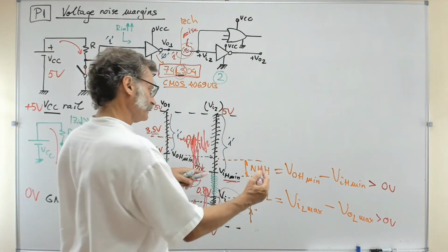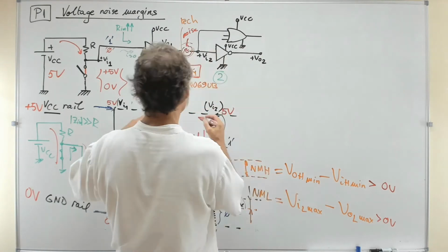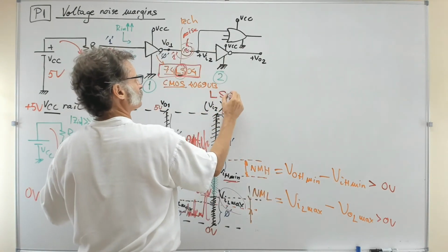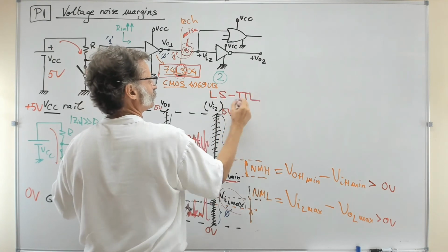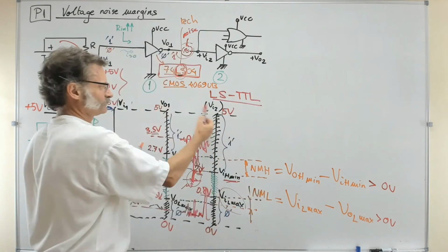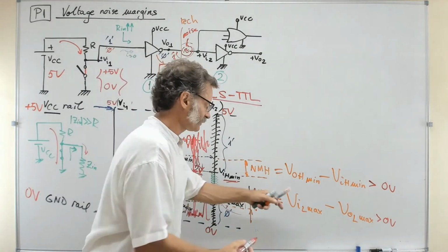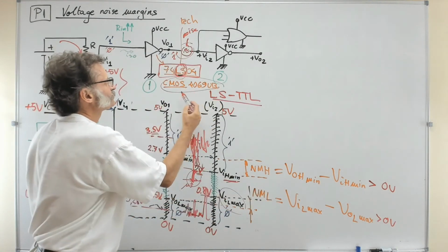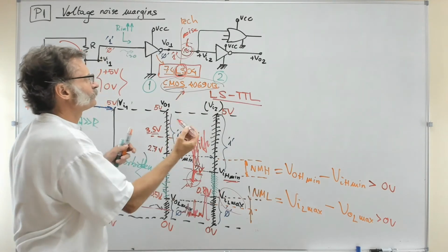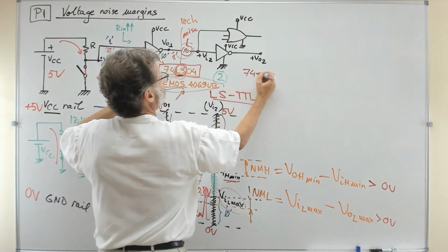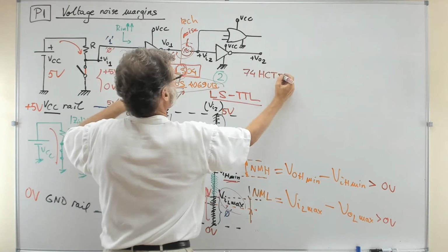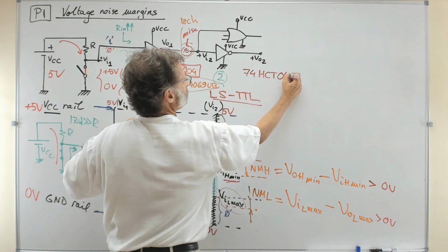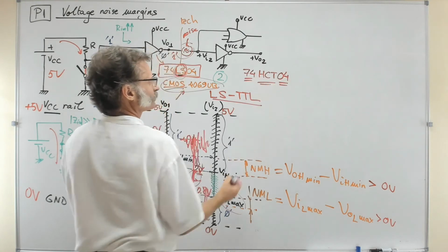So in that case for TTL, you see, from Schottky low power TTL, a very old technology today, but for the sake of understanding, this is okay. You can do the same calculations later by your own, changing to a CMOS technology or the same chip, 74HCT. That is an advanced one. The same chip, you see, but with this different technology.